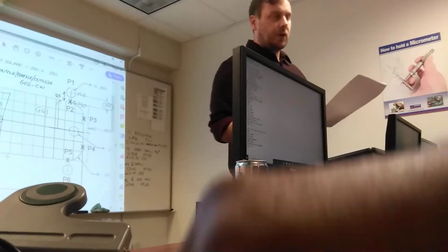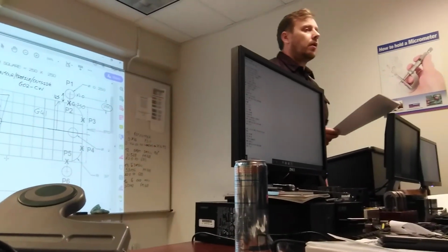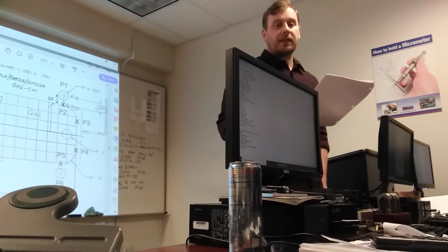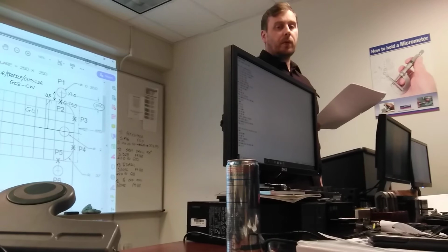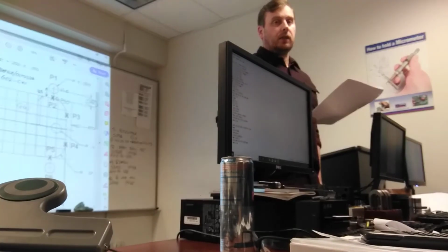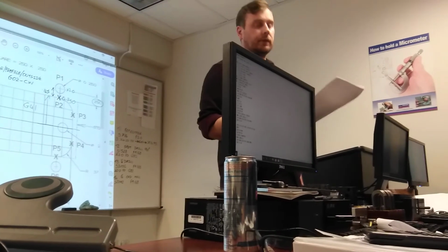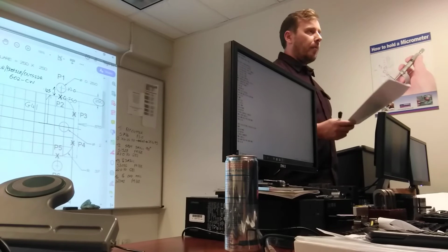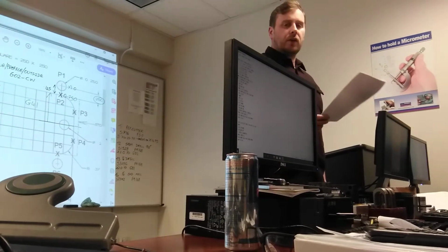Highlight all of number 2. Do not cancel cutter compensation on any line that is still cutting the part. One up. You're highlighting the wrong one. Number 1. When activated, you're looking at deactivated. Oh, bring the Z-axis down. Always bring the Z down before you activate cutter compensation.